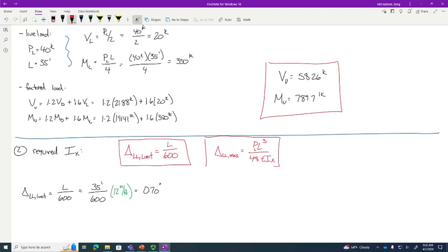This is our expression for maximum deflection, right? So again, it's very tempting to do this, but no. The same thing I said about strength is the same thing I said about deflection. Which do you think is going to cause the beam to deflect more? Spreading the load out or lumping it in the middle? Lumping it in the middle, right? So, for this beam, what do we know?